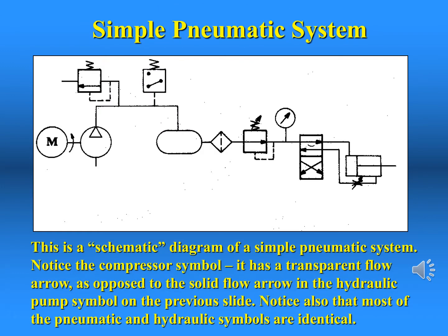This schematic drawing is a pneumatic system. To begin reading, identify the power unit on the left and then trace the path of airflow out into the system toward the actuator. The connection of the line at the top of the receiver tank is no longer used and is supposed to enter the tank from the left side, maintaining parallel symmetry with the outgoing line on the right.